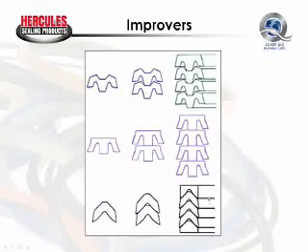The V-packing, however, on the other hand, is a gland sensitive type of ring. It has multiple rings which seal more effectively, but when you shorten the axial length of the gland, you're actually squeezing the sets together. This adapter ring pushes up into the cavity of this free ring, causing this lip to flare out with a greater radial flare. The crown of this V forces into the cavity of this one, causing it to flare out, and so on up the stack. So by shortening the axial length of the gland, you can create a greater amount of radial flare of these lips and make the set adjustable.